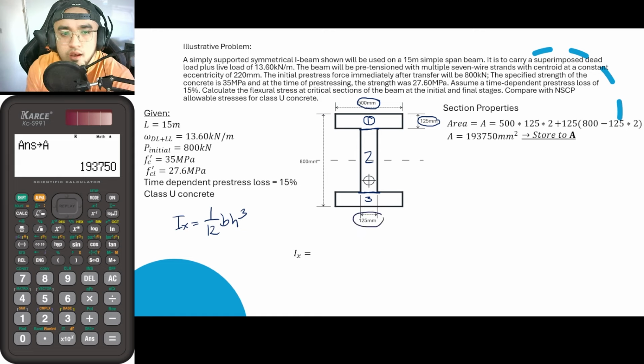Take note that if you would be making use of this formula, what you did was solve for the moment of inertia about this point. Apologies for drawing not a straight line. And if that is now the center of your moment of inertia, you should transfer it here, since the centroid of that rectangle did not coincide with the centroid of your figure.